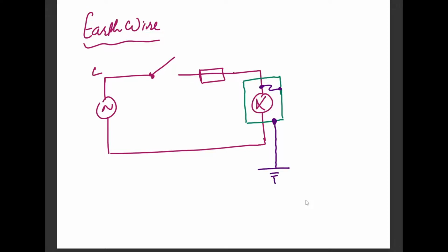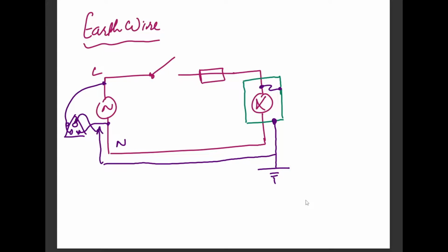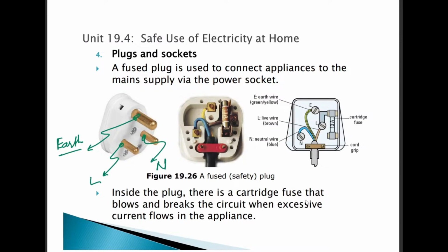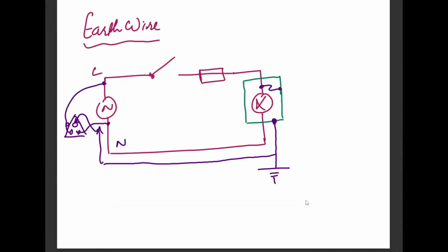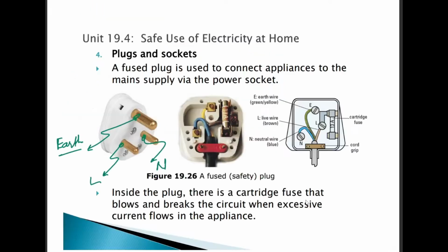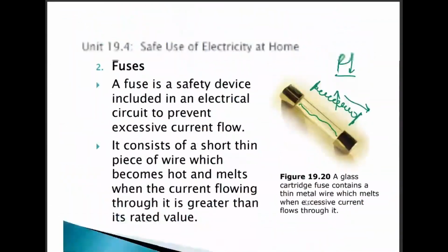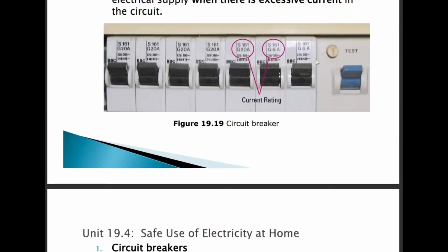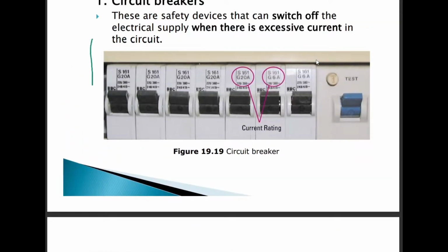What we do with this third wire in real life is I bring that third wire back along the neutral wire and then bring it back over here, and I connect it to the 3-pin plug that we have. So one has the live wire, this one has the neutral wire, and the third pin has the earth wire connection. So do we understand how we're connecting all the 3 pins of this 3-pin plug? Right? Yeah. And of course this earth wire, in the distribution box of the house, they will connect this third wire, the earth wire, to the ground of the earth.